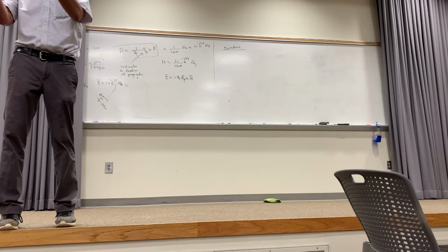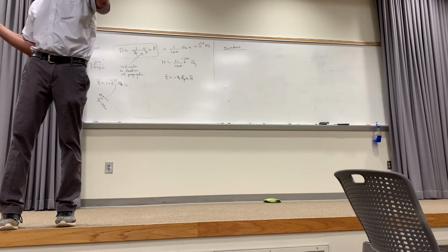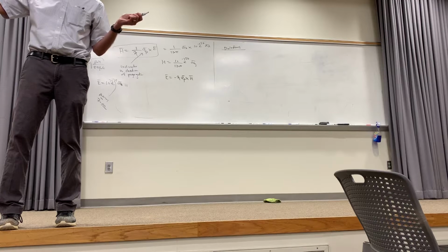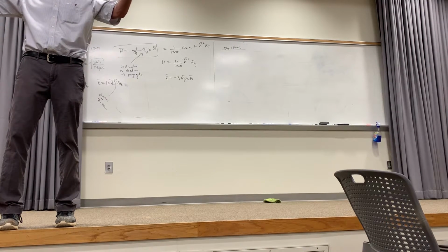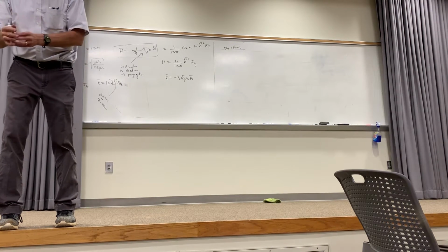If I charge up a capacitor to 5 joules, I can burn 5 joules in a resistor if I discharge it. Now with an inductor, you have magnetostatic energy, and the energy in an inductor is 1/2 Li squared, isn't it? That energy is from a static magnetic field around that inductor, and when you short that inductor with that current into a resistor, all that energy is deposited back in there.